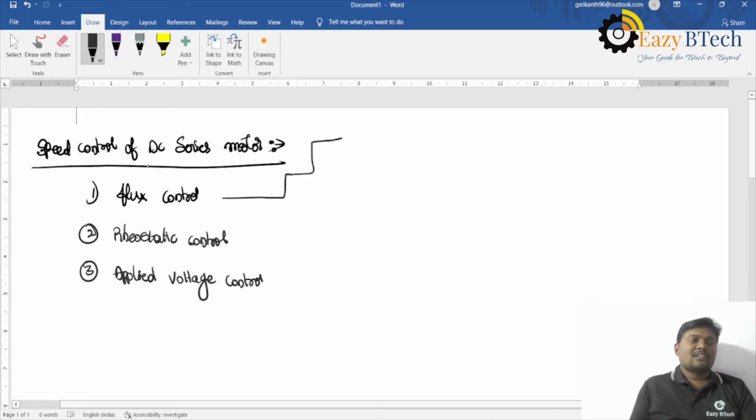In this lecture, I will explain speed control of DC series motor. The first method is flux control, the second is rheostatic control, and the third one is applied voltage control.